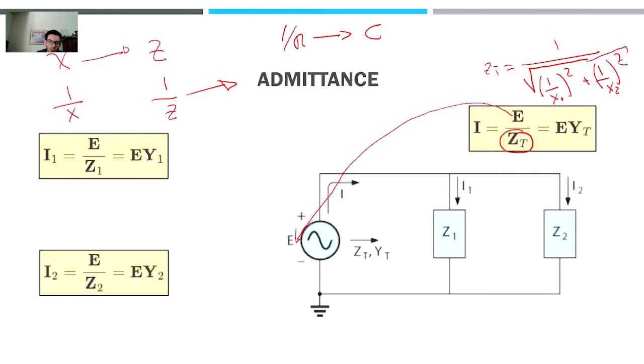Okay, 10 volts, 120 volts, wherever it is. Now, since you know from DC circuits that in parallel the voltage through each branch is the same, V1 equals V2. So what we do now is compute the currents through each branch, which is not going to be the same. And we do that by simply taking the voltage, which is the same, over the impedance or the reactance of the first element.